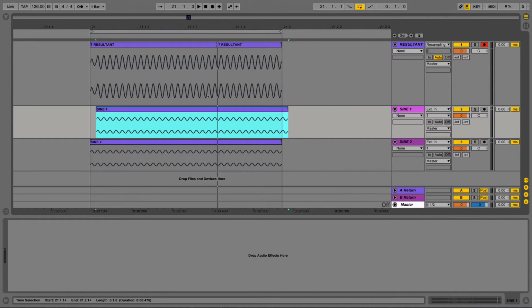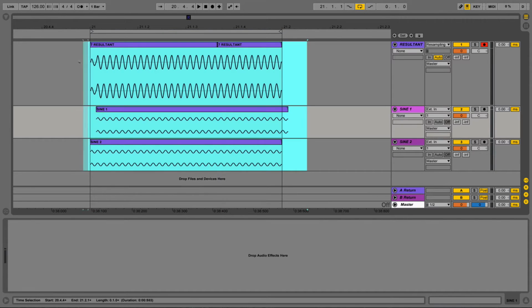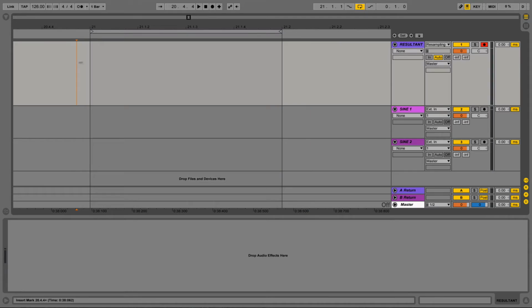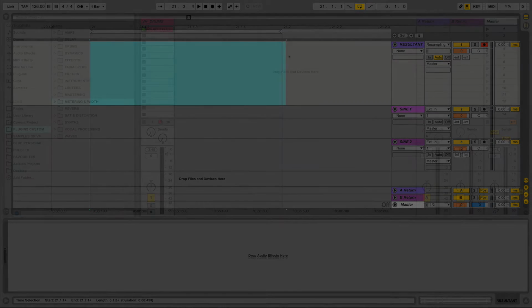So if we think about that with a more complex sound, obviously this is just with a sine wave. If we think about that with a more complex sound such as a piano, which is made up of hundreds of sine waves, each at different frequencies, then as we start to split a sound into the left and right channel, when we start to add a time delay to one of the channels, we're going to get this effect at certain frequencies. So we're going to get notches at certain frequencies throughout our frequency spectrum, which is going to give us that phasey type sound, which is not what we want.